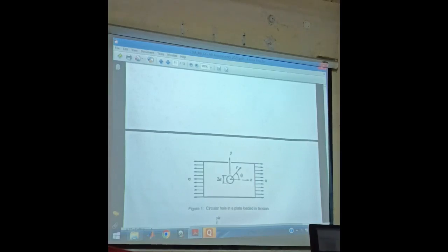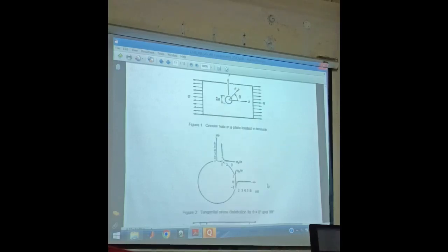That means if it is axial load along the x direction, its length is not important for the area, but the cross section is important. If the thickness is the same, then the width is important. Now when the width is comparable with the radius of the circle, there will be some effect. For Kt, the stress concentration, we know it will be 3, but it will be more than 3. That concept can be utilized here.